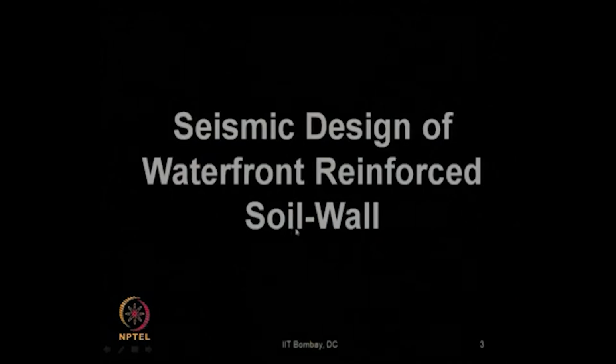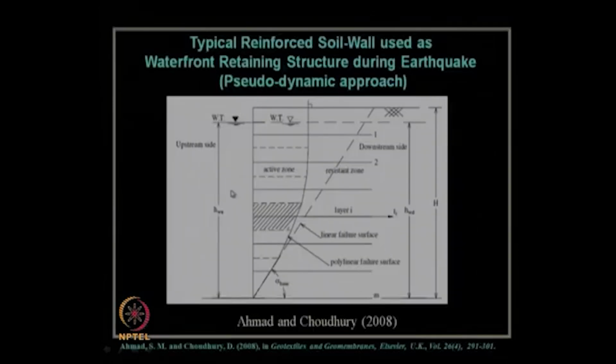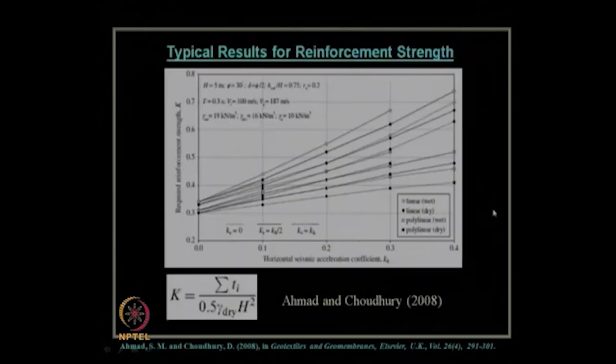We studied the seismic design of waterfront reinforced soil wall, that is, the analysis of reinforced soil wall in the waterfront by using pseudodynamic approach, both in terms of internal stability as well as external stability. The internal stability is from the paper by Ahmed and Chaudhary, appeared in the journal Geotextile and Geomembranes, Elsevier publication, 2008. We mentioned how to find out the required reinforcement strength to be provided for internal stability.